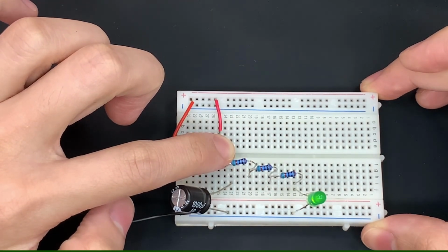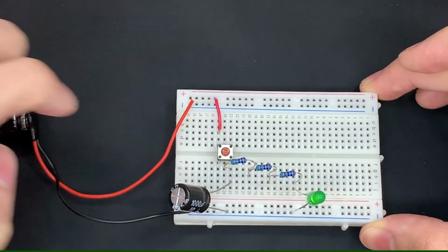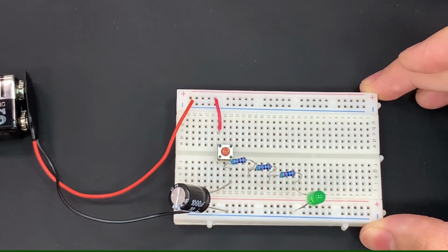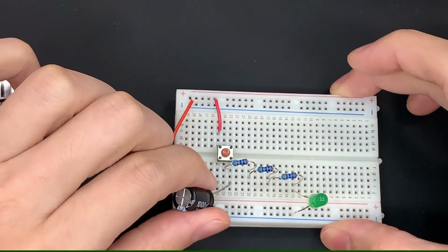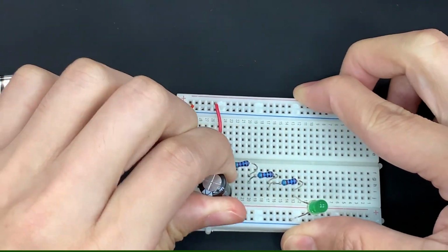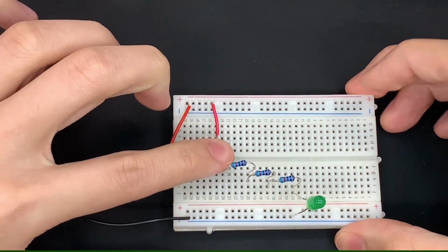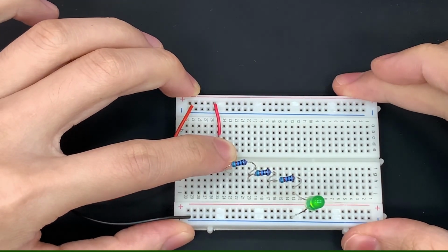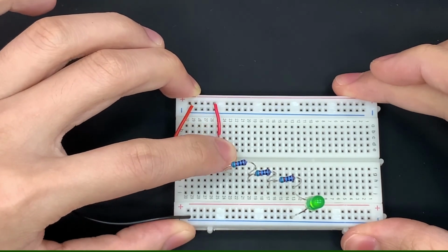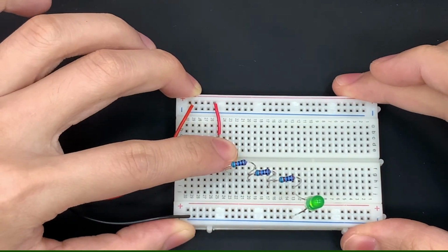Holding on to the push button for a longer period of time will allow the capacitor to build up more charges. And you can see again that the LED did not go off instantly. Let us now take a look at the circuit when we remove the capacitor. When the push button is pressed, you can see the LED lights up. However, when we release the push button, immediately the LED goes off. This shows how a capacitor is useful in a typical circuit like this.